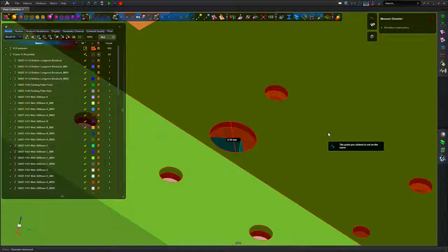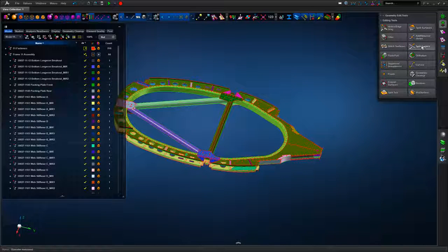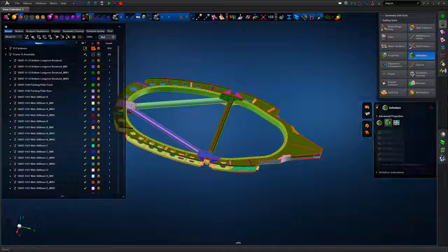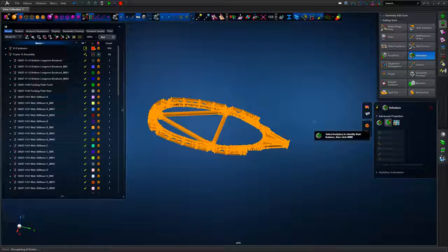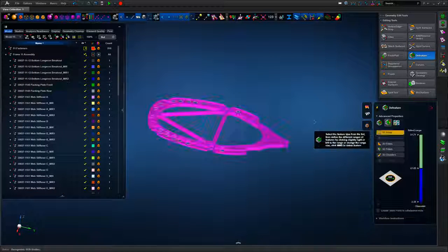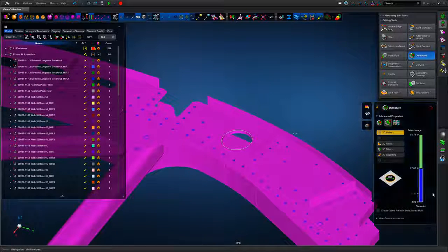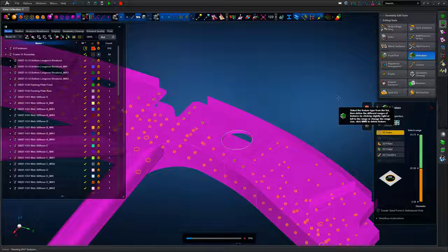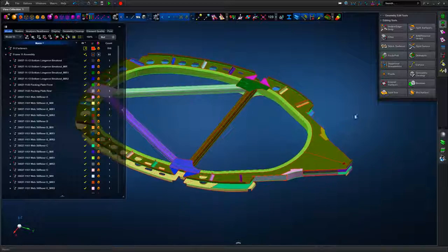And if we put the full assembly on, we can see how that manipulation has been defined within the full assembly. So measuring some of the hole geometry, just getting the hole diameter, 6.35 millimeters, and we're now going to defeature all of those surfaces to remove the 2D holes, again less than 6.35. Apex has done a good job in highlighting the small and large holes. So we're going to leave the larger holes, and then all of the holes defined in blue in the fringe plot on the right hand side, simply select them and then middle mouse button to accept, and Apex will remove those from the resultant geometry.